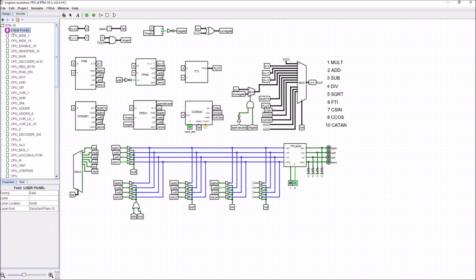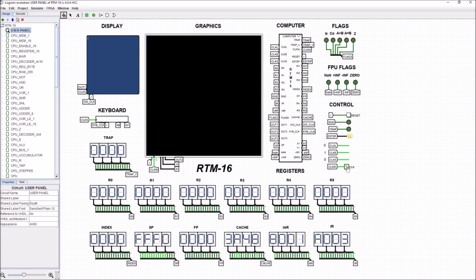So we worked through all of the rest of the micro instructions, and the final value we get out is going to be in register R3, which is 39AC. So 39AC is going to be approximately 1 upon root 2, which is 0.707.